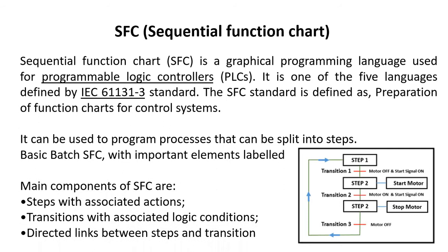The basic SFC has important elements. First element is the step, which is associated with actions. Second element is the transition, which is associated with a logic condition. Third element is directed links, which join both the transition as well as the step.